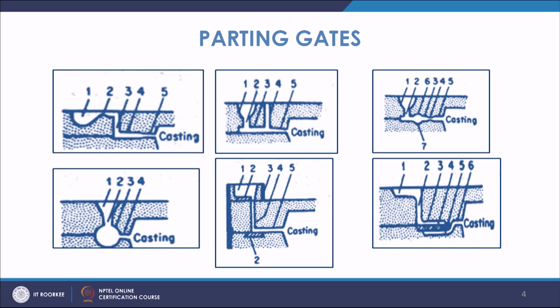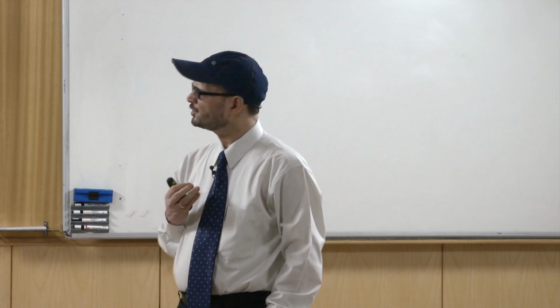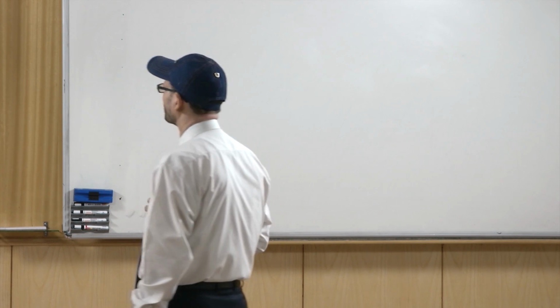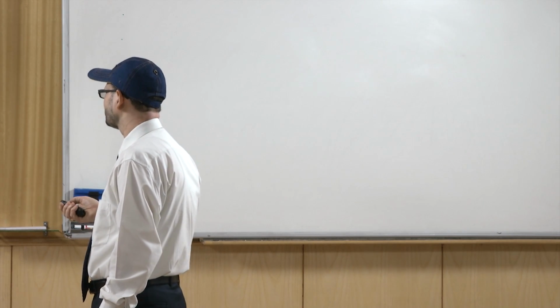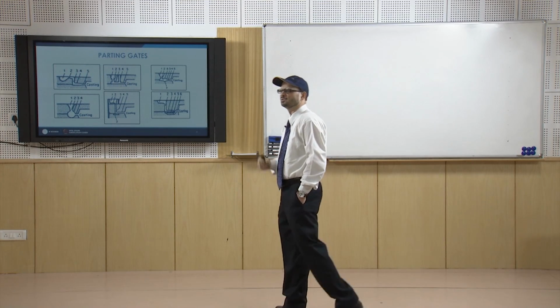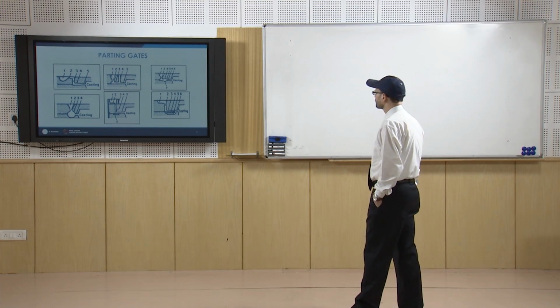So, they will be collected in this portion. These relief sprues have two functions. One is to relieve the pressure if there is a pressure increase at some point, and another is that they try to collect or separate the dirt or any foreign impurity flowing in the stream, and then you have the gates, and further it goes into the casting.